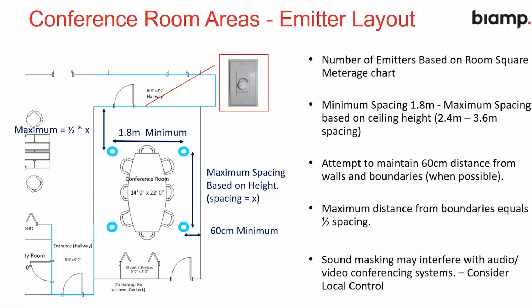So conference rooms are generally the same rules as a closed space if they're small enough, or if they're a larger conference room, then you might go up to the standard rules. What I would be wary of with a conference room is you do not want the sound masking too loud in a large conference room, because it will defeat the object of the conference room. However, a conference room with sound masking at a lower level will make the meeting room slightly more private. We also consider using a volume control unit or a room control unit to mute the sound masking if required.